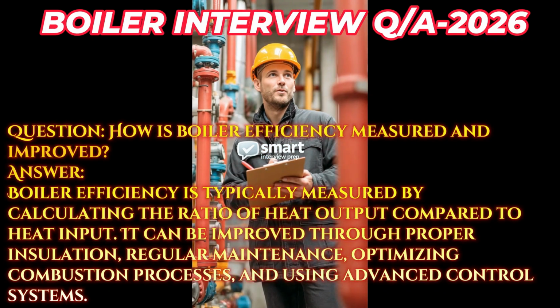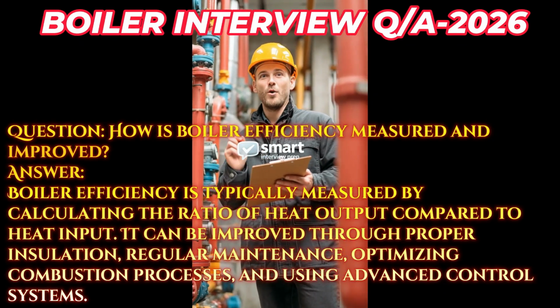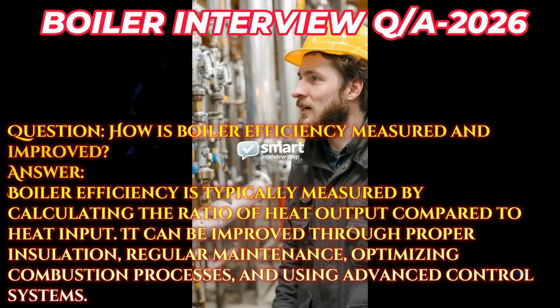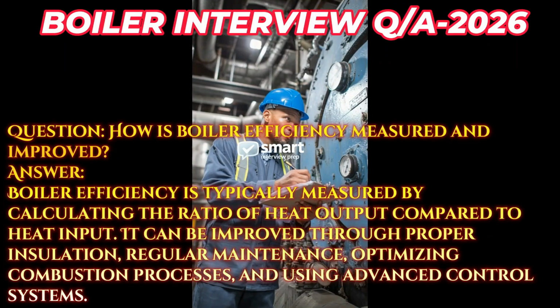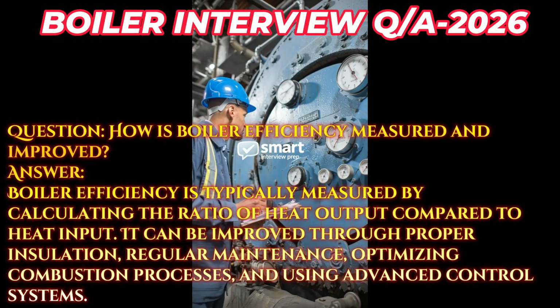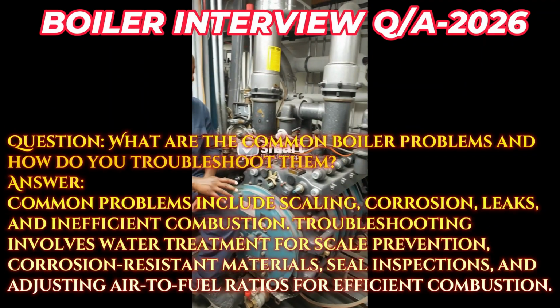Answer. Boiler efficiency is typically measured by calculating the ratio of heat output compared to heat input. It can be improved through proper insulation, regular maintenance, optimizing combustion processes, and using advanced control systems. Question. What are the common boiler problems and how do you troubleshoot them?